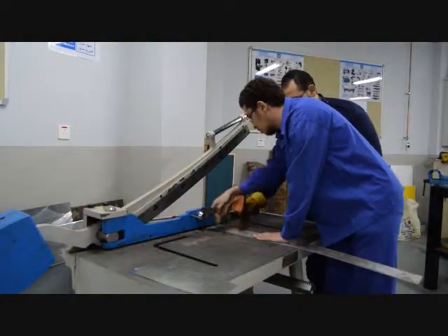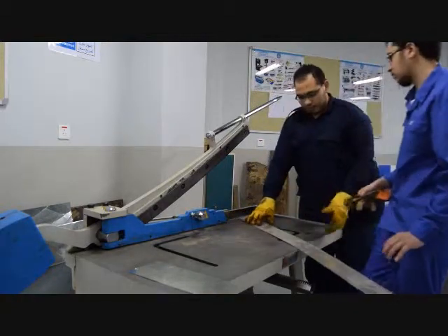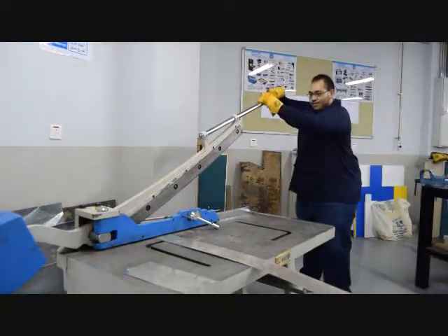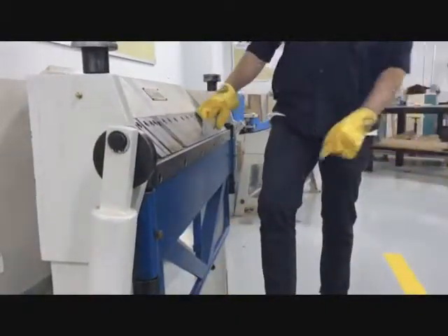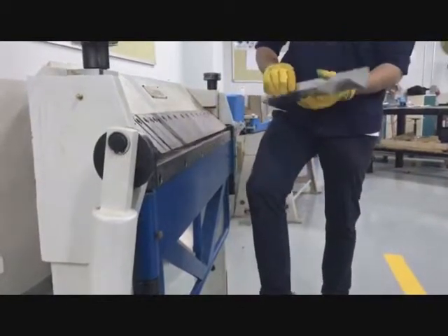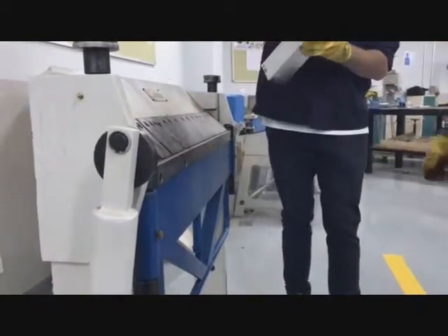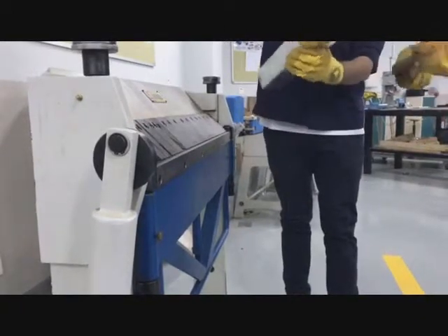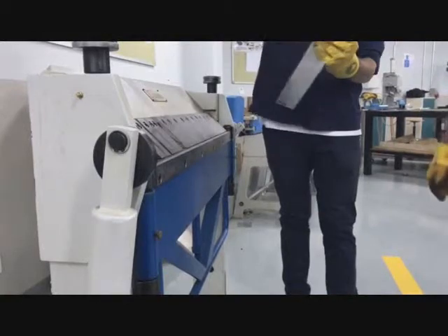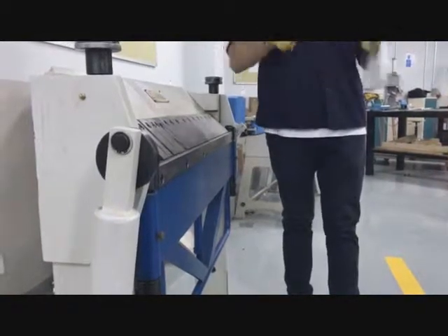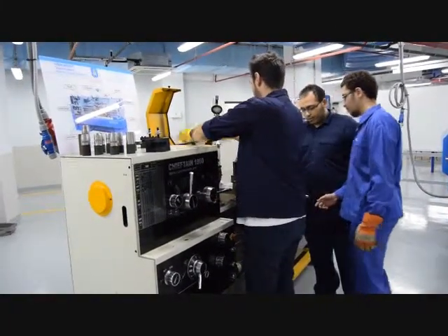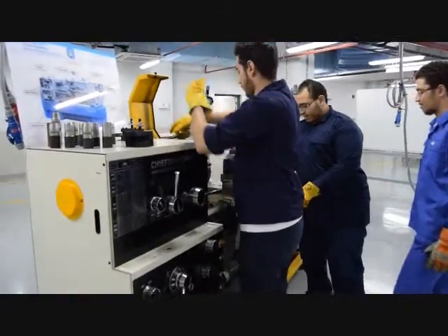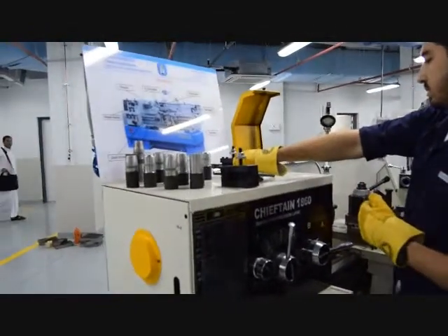And once it breaks, there will always be three things you have to keep in mind, which are shear force, bending moment, and normal force. Regardless of the normal force, because it depends on the reaction force that acts horizontally with the beam, the shear force and the bending moment have maximum numbers. And it's so important to know where exactly the maximum shear force and maximum bending moment are, in order to put specific materials to strengthen these weak parts, avoiding any failure.